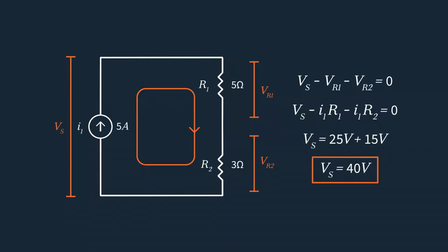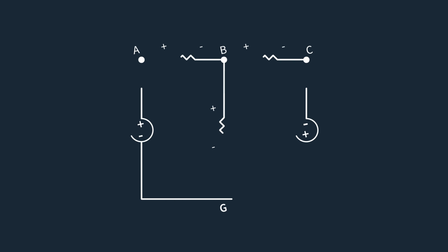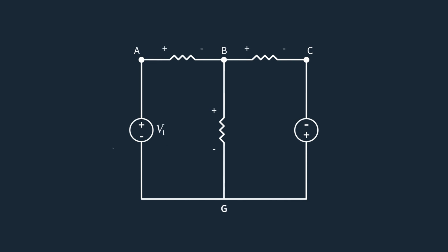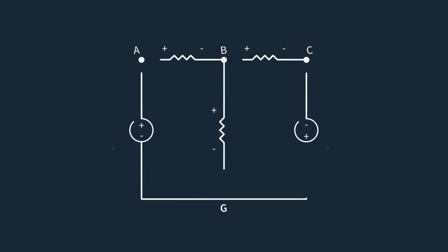For our second example, let's consider a given circuit with two loops. There are two voltage sources, V1 equals 5 volts and V2 equals 2 volts. Currents I1 and I2 pass through loops 1 and 2 respectively, with resistances R1 equals 2 ohms, R2 equals 3 ohms, and R3 equals 1 ohm. Using KVL, let's find currents I1 and I2. Let's look at this circuit.